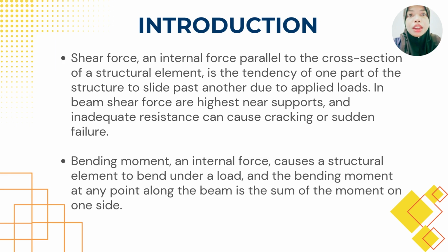This slide introduces shear force and bending moment in beam. Shear force is an internal force that is parallel to the cross sections and usually higher near the support, where failure may occur if resistance is insufficient. Bending moment causes the beam to bend under applied load and is calculated as the sum of moment at a point along the beam. Both are important for ensuring structure safety and proper design.